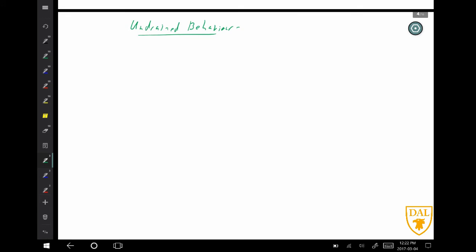That's like conditions where the hydraulic conductivity is quite low for the most part. So a clay is a good example of a material that often behaves in an undrained manner, but not always. Again, it's relative. It depends how fast it's being loaded relative to its hydraulic conductivity.